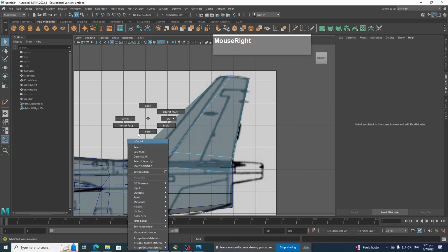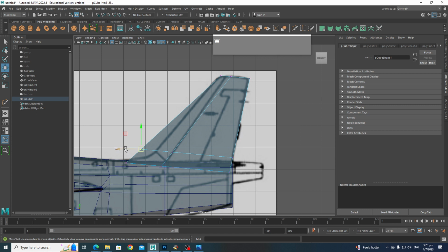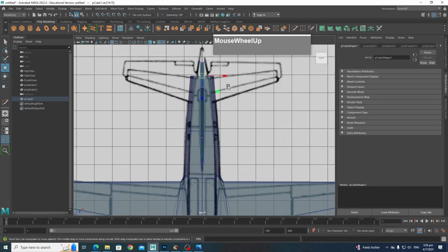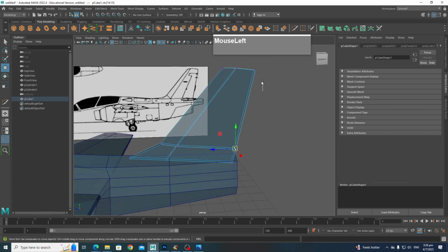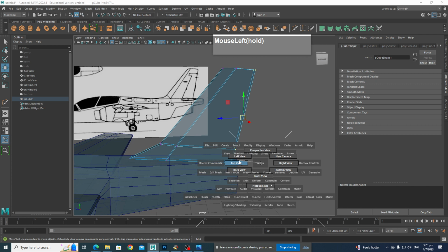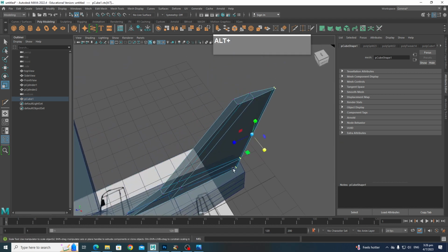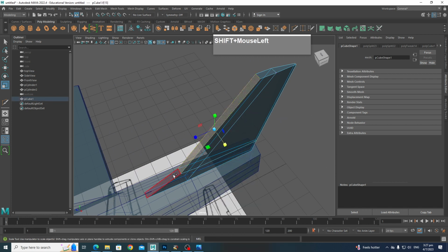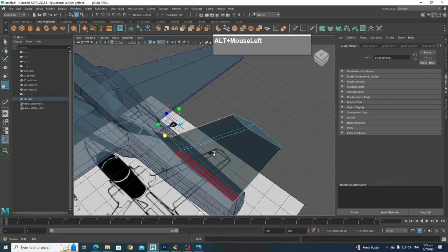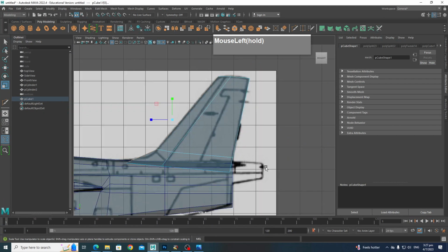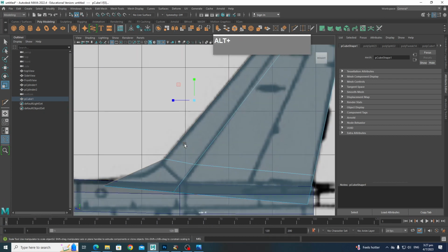Alright, so right now I want to create a rounded nose section of this leading edge of the tail fin. And then the tail part here should be narrower, so go to the top view. Okay, we need to select this group of vertices here, go to the top view, and then use scale to scale it down so it becomes tapered like that. And the front part of these faces, you can select the face here like that, and just scale it inwards so that they form this cross section. Then we have our vertical tail fin.